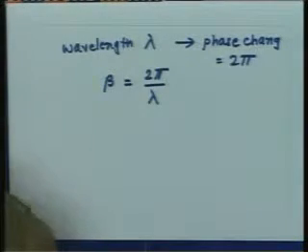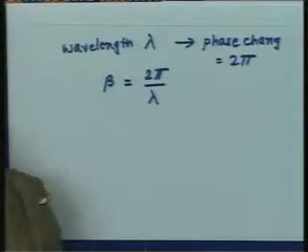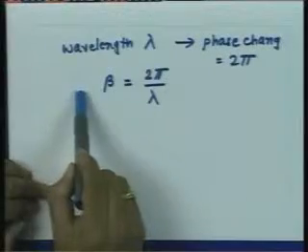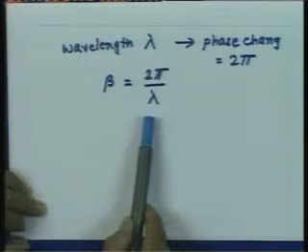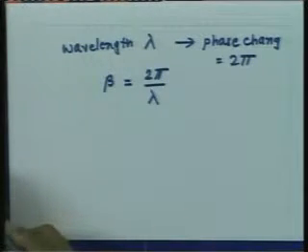In fact, in wave motion lambda is not the one which is first determined. In a complex geometry of wave propagation, first you analyze the parameter beta, and then by using the relation 2 pi divided by beta you get a number, that quantity you call the wavelength. For a simplified problem we know the velocity, and from the velocity divided by the frequency we get the wavelength. However, when you have a complex structure on which the wave is propagating, the velocity is a parameter which is unknown. In other words, this quantity beta is unknown. So, normally when we have a wave analysis problem, first we solve for the parameter beta, then 2 pi divided by beta gives you a number with a dimension of length, and that quantity is called the wavelength of that particular wave.